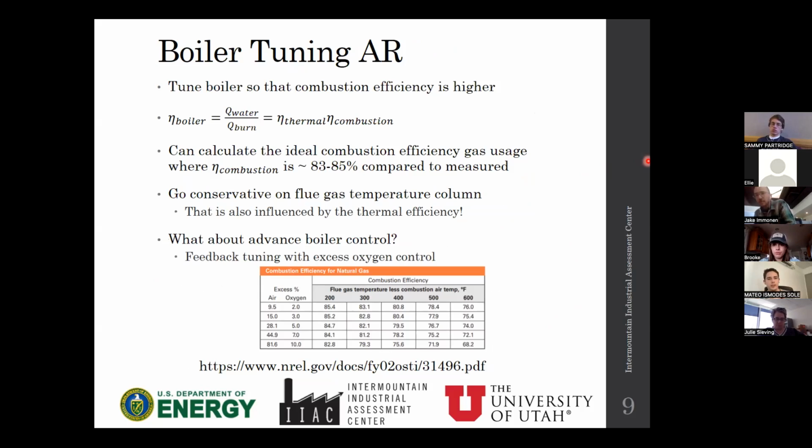A type of compressor that I've seen in the past is a centrifugal compressor. The one I saw was over 1,000 horsepower in size. The problem I found when trying to find savings was that the rate of savings per CFM was really different to a rotary screw compressor.